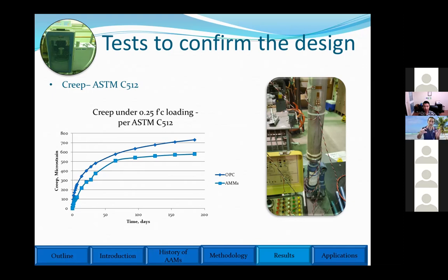If you calculate the instantaneous deflection, for example, 1 inch for your beam, this 1 inch will increase to 2 inches after 5 years, and it's going to be problematic. But for alkali activated concrete, it's safer. At least after, for example, a couple of months, you can install your, for example, elevator.